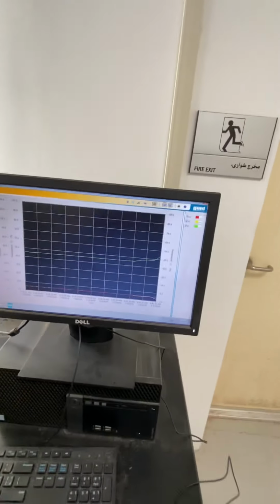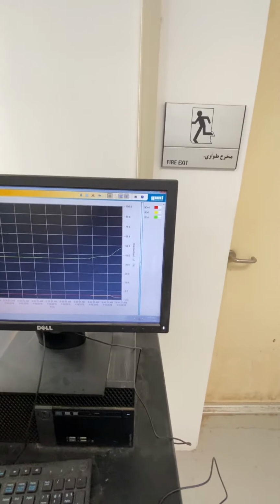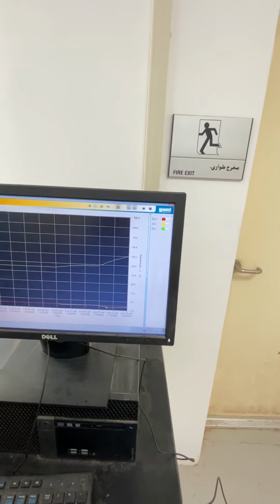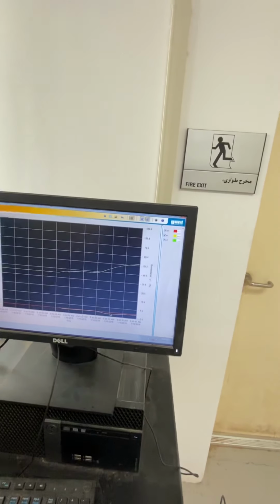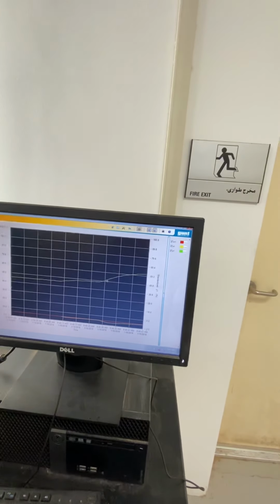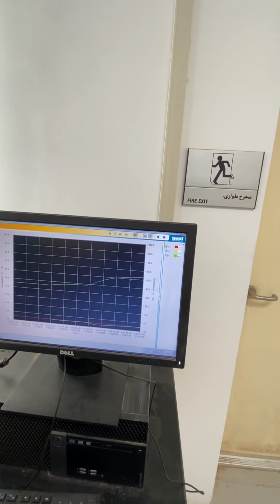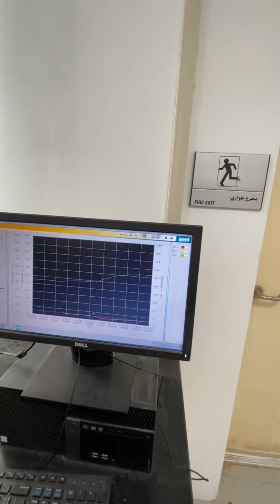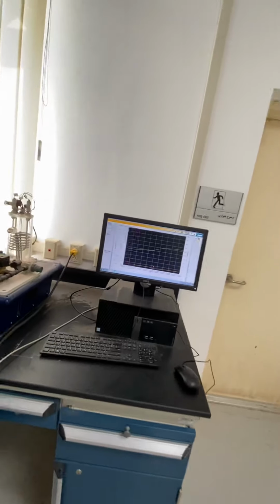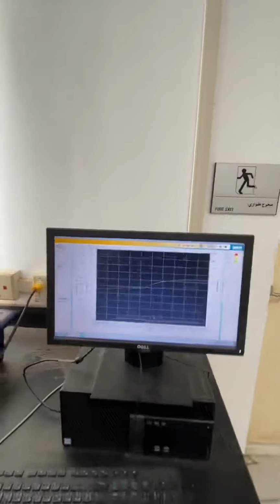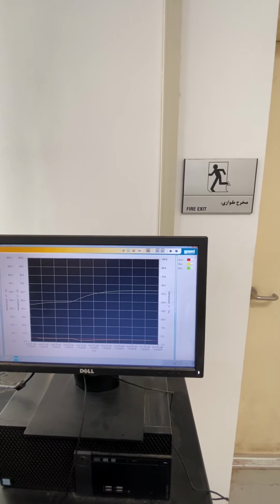So by reducing pump speed, as I said, the flow rate will decrease, and you can see right now that once we have a negative error, which is the yellow minus the red line, the process value minus the set point, the output signal started to increase. So again, reducing pump speed causes the process value to go below the set point, and that creates a negative error, and as a result the output signal started to increase, as you can see here.